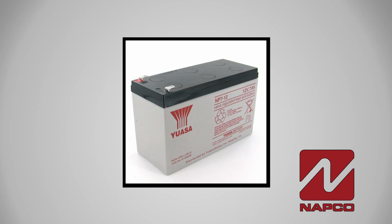While we're at it, here's a bonus tip. High voltage can cause the radios to behave strangely. If you have high power or dirty power that you think may be causing issues on your radio, you can test the radio by wiring a 12 VDC 7 amp hour battery directly to the radio on screw terminals 1 and 2. Make sure you disconnect the power you originally had connected to the radio before you make the battery